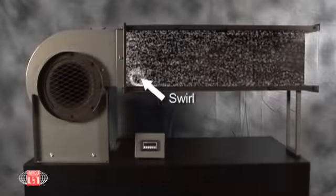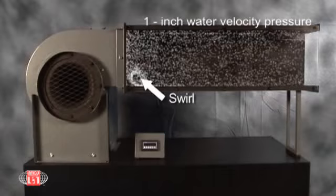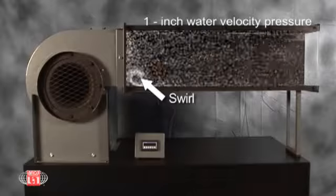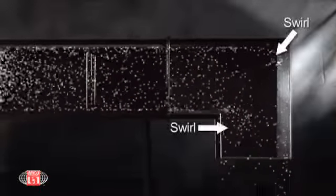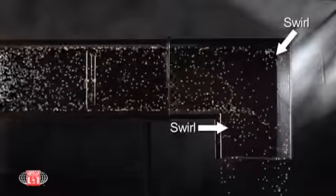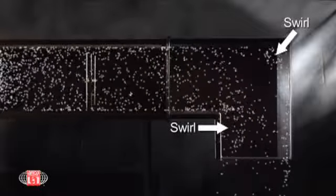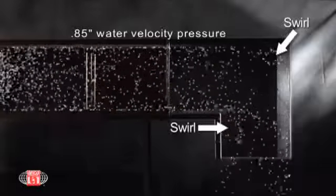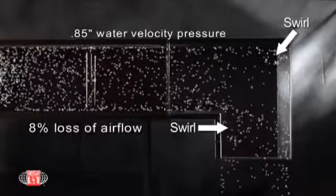The second major impact involves proper fan outlet design. The same elements that have an impact on inlet design, namely ductwork and dampers, also have an impact on outlet flow. Let's assume 1 inch water velocity pressure on the outlet side of a fan, similar to the inlet side in the example just given. If we add a right angle elbow on the outlet side in the direction of the fan's rotation, we reduce the velocity pressure to 0.85 of an inch water velocity pressure, which is an 8% loss of airflow.